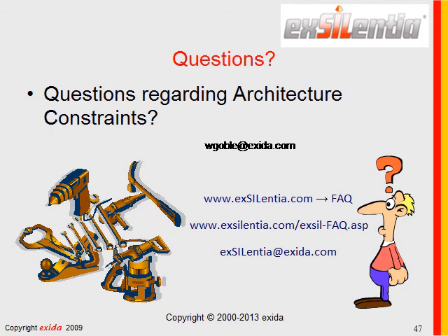Okay, a comment. So, is 2H basically certified, proven in use? Well, 2H is not the same as product certification. So the question as stated, no, it's not the same thing. But is Route 2H the same as prior use or proven in use?